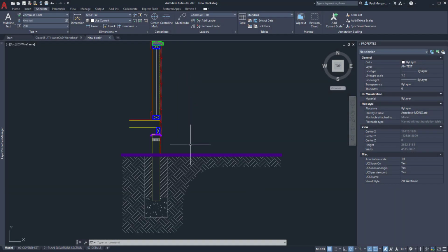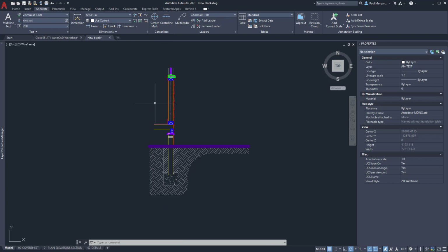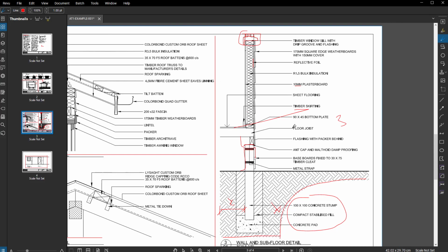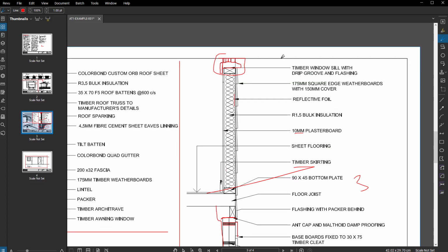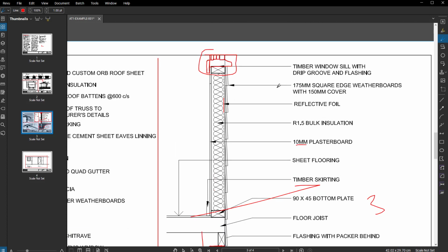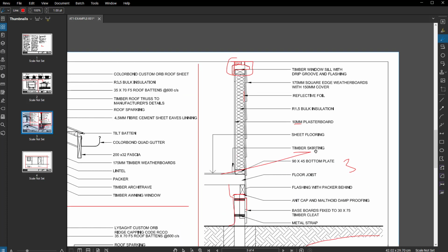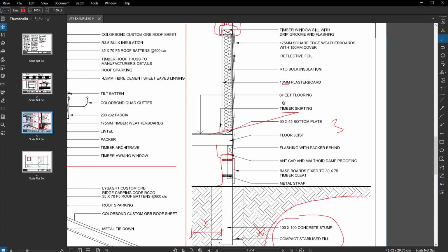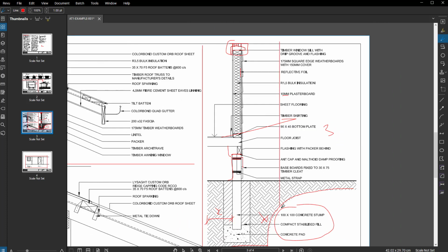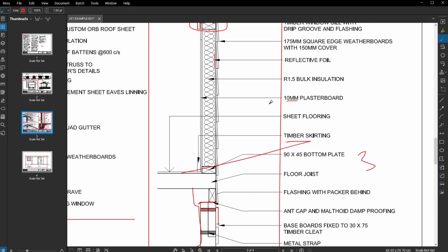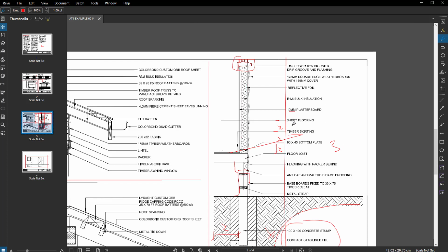Right, so I'm happy with the way that this has come up. I'm completed with detailing up my drawing here. So I'm going to go back to my example, and you'll see here it's time to add some text. So these are called multi-leaders. It's essentially text with an arrow. That's that simple. One thing that we'll notice for starters is that they're all in a row. So you can see they're all aligned, that they're relatively spaced apart, and that the spaces apart are, generally speaking, about the same distance apart. Not always, but most of the time they are.